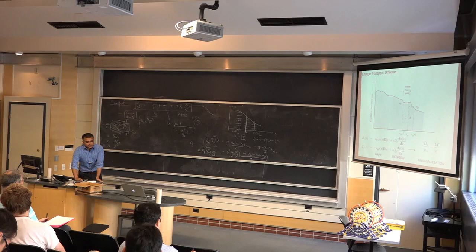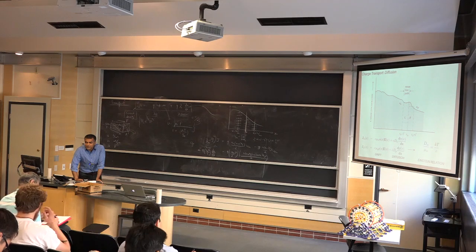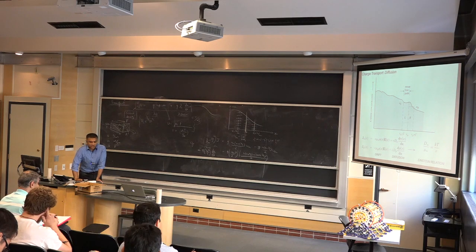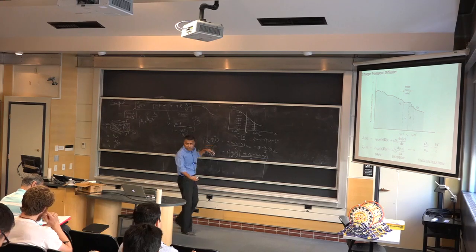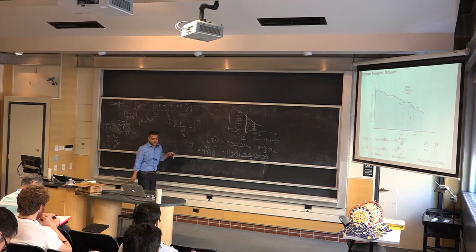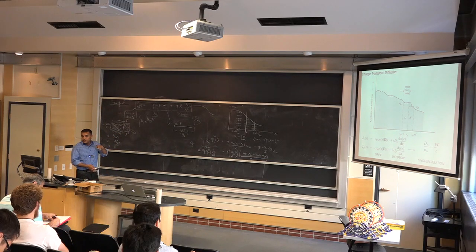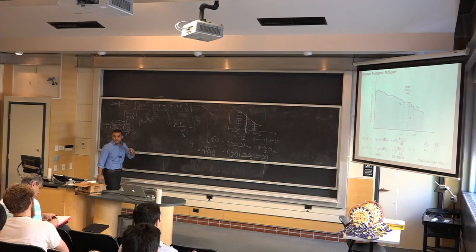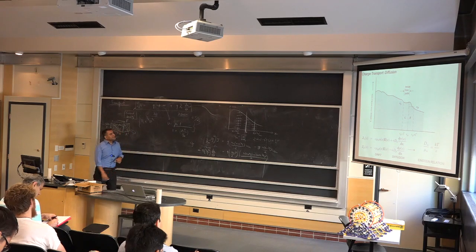Yeah. The band diagram is flat, and n of x is constant. And you have equilibrium. That's correct, that's exactly right. If the electron density is not changing, then there's no diffusion current. That is correct. It's just solely drift. Then it can be drift if you apply a field. Yeah, if you apply an electric field. If not, it is 0, but the net current is 0.